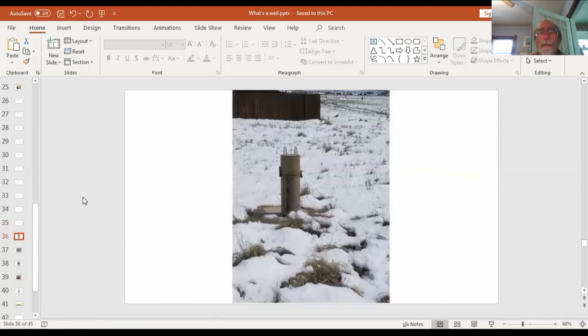What does a well look like? What does groundwater look like? This is always a frustration because we hydrogeologists don't have much to show, like a big bridge or a new school building. This, for example, is the Imperial Heights South Monitor well. Nothing very exciting there. Poured a little cement around it to keep your feet from getting muddy as you're sampling it, and to keep surface material away from the wellbore itself. Typically, what you'll see in a PVC well, here's that PVC casing, and the steel is just a guard casing. So the steel is planted in the ground 4 or 5 feet. It's just to keep people from running into it and breaking it off. But this is what you see inside a typical monitor well.